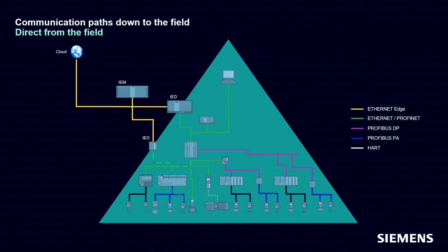In any case, you must be able to establish the communication with the Profinet devices without interrupting the communication with the controller, which would lead to a disturbance of the running automation process. And we don't want to change the controller's program. From the connector's point of view, you must be able to handle the communication topology down to the field devices and reuse the communication layers, which are the same, to address this complexity. On this topic, we are currently working and call it Cascaded Connectors.